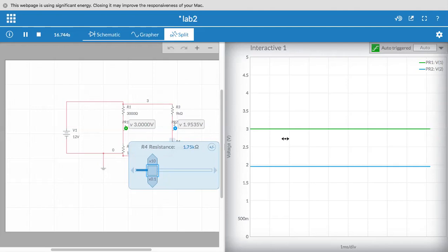A bridge is used to convert the sensor's resistance variation into voltage variation. In this case, I just demoed the voltage as temperature drops: the voltage goes from +1 all the way to 0, all the way to -1.